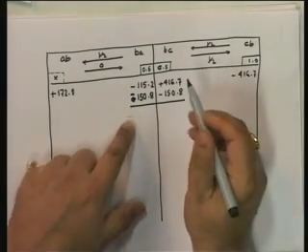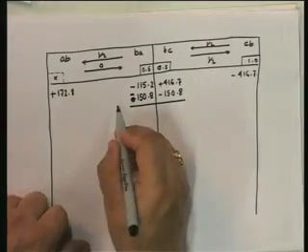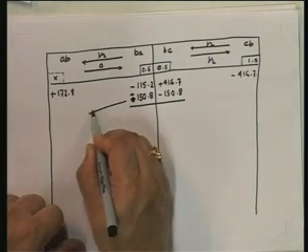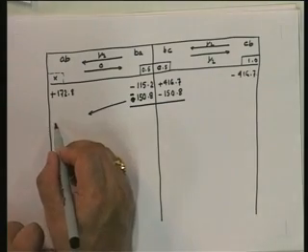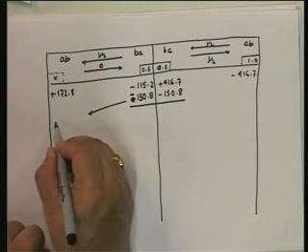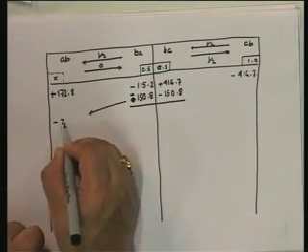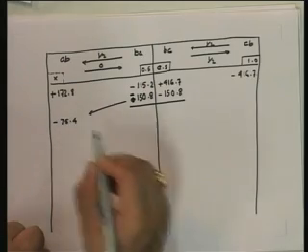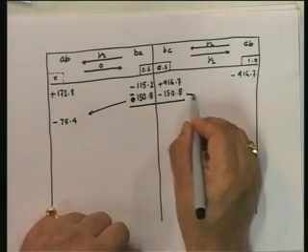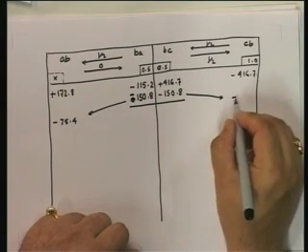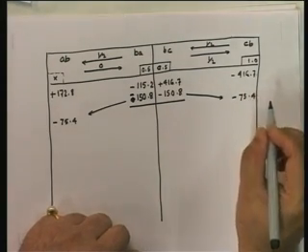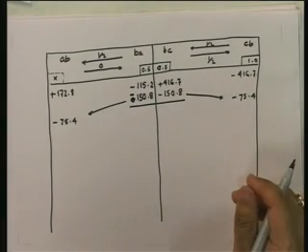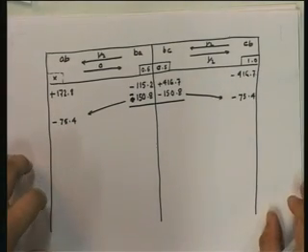And now note, I will have to carry over these, because as soon as I release this, I have to carry over here. Carryover is half. So what do I get? Minus 75.4. Here I have to carry over half. So I get minus 75.4. Okay. So if you look at it, what do you get?